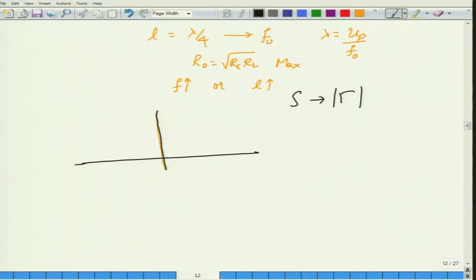So let us look at two cases. First, we assume that the normalized impedance is twice the characteristic impedance, that is a 2:1 ratio in which you are trying to match, or you might be trying to match, say, a 4:1 ratio. If the normalized load happens to be about 4, then you see that for the two cases the VSWR starts to worsen.